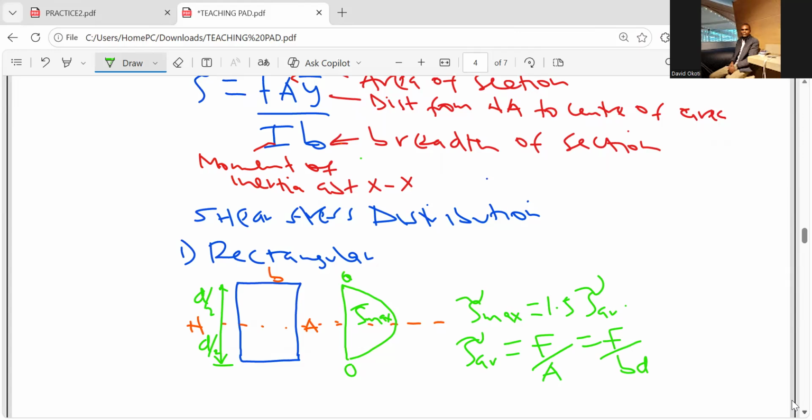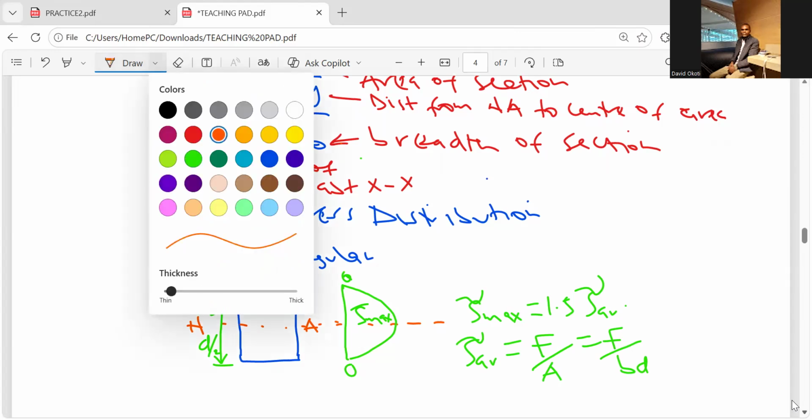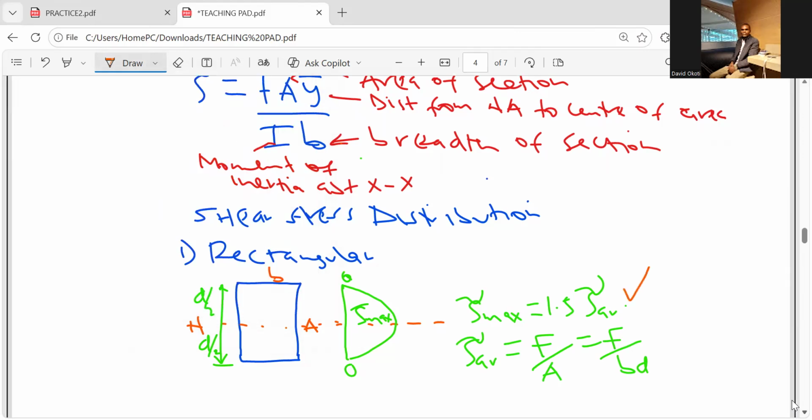In design of timber, this is where you will appreciate the use of this maximum shear stress. During design of a timber beam, when we are checking the compression stress at the support, we use the maximum shear stress, given by 1.5 times the average shear stress, which comes from the applied force or the reaction FV divided by B times LB, where LB, if it is a wall, we call the length of bearing.